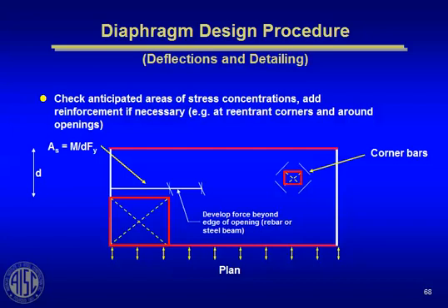You got a sort of a shear concentration of force right in that coped area, and that may require some additional reinforcing steel right here to take the bending in that dapped area, and then you got to check the shear in that distance D. Be sure that your shear isn't too high. If it is, you may have to reinforce the diaphragm along that area. So be watchful of openings in diaphragms. They can create high shear situations.